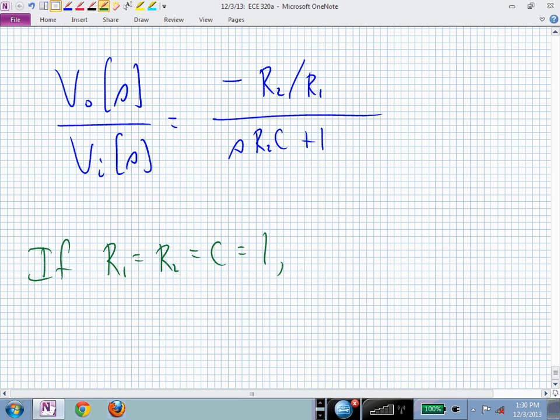And if I neglect the negative sign for now, because now what do we know about that? That's just going to change the phase curve, and it's just going to lower the phase curve by minus 180. So if you will allow me, I will neglect the minus 1, and I will simply say that Z sub f over Z sub I is now S over S plus 1. Is that okay?